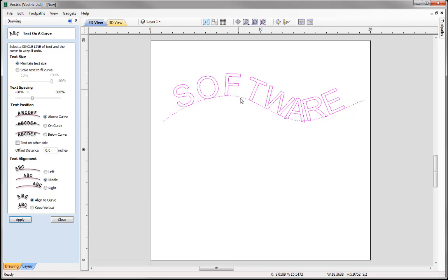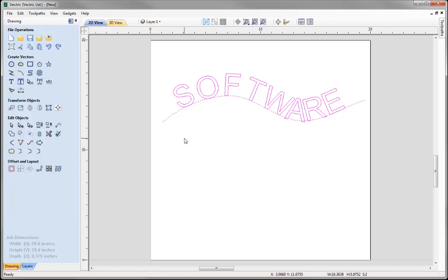However, what I would like to do is just go in and edit the individual character spacing. We can't do that in this form. So let's just close that down, and I'm going to come back over to edit text spacing and curve, in which case I can come over each of these letters once I've selected that word, and I could just decrease the space in between the letters like so. Here I could look at increasing, so holding down shift to increase that spacing, and you can see that every time I'm making an edit, it's still following the curvature of the curve that we originally aligned that text to. So I like the way that this looks.